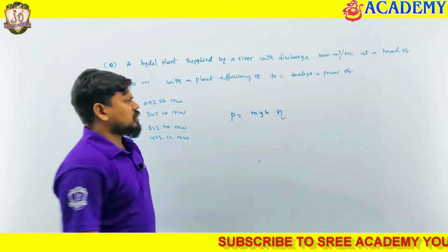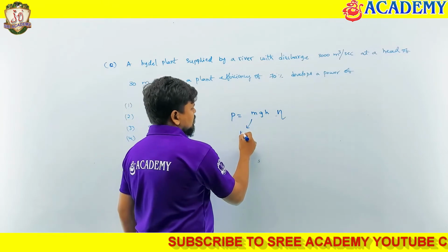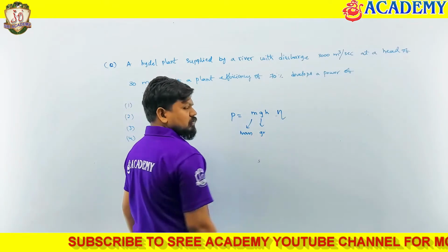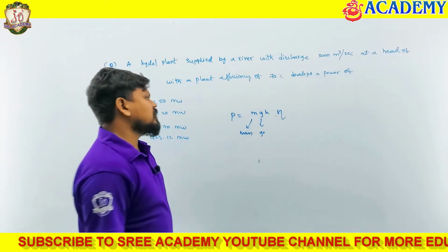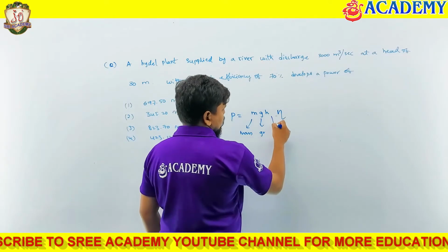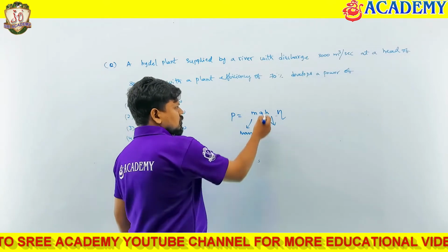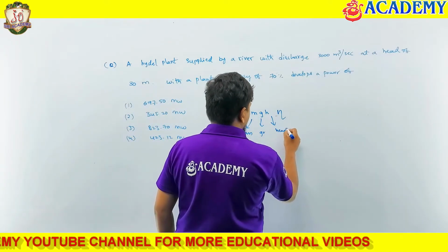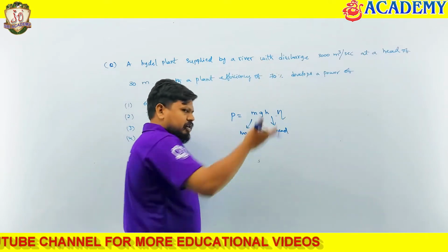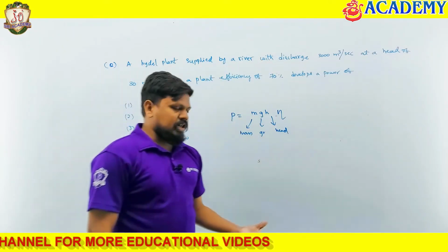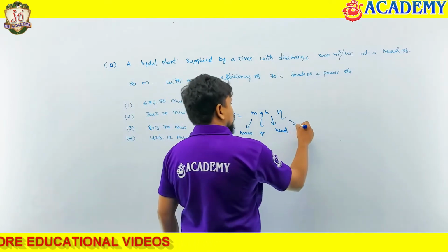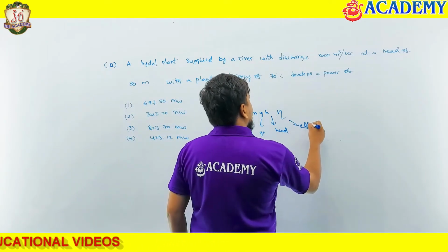So m is nothing but mass, g is nothing but gravity. Gravity we know, right? What is the value? 9.81. So this is the gravitational constant. h is nothing but head, the net head of that plant, that is, from how much height water is coming and hitting the turbine. That we have to take. And efficiency, you know already, this is nothing but efficiency.